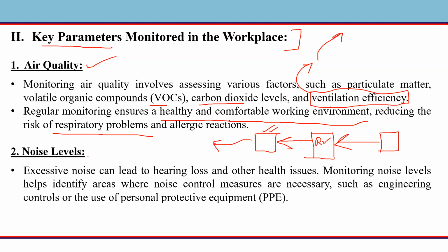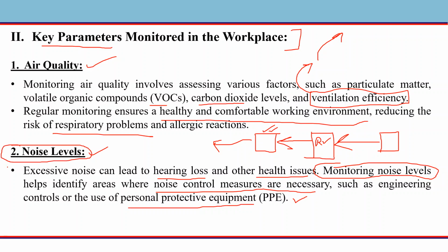Then we have the noise levels. Excessive noise can lead to hearing losses, right? Or other health issues. So, monitoring of these noise levels is very important, and it helps identify areas where noise control measures are necessary, such as engineering controls or the use of personal protective equipment. This is done to assure that the employees do not have any health issues related to their hearing.